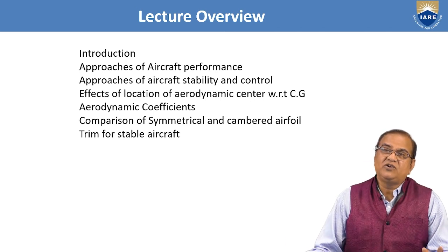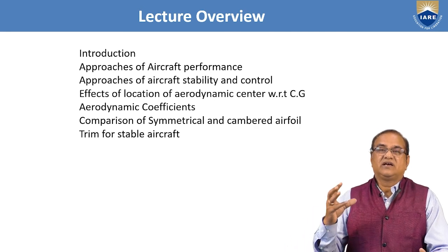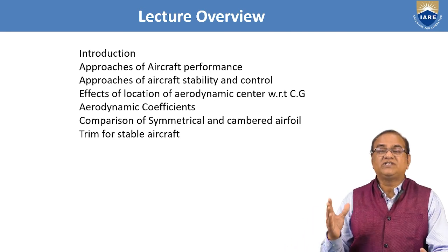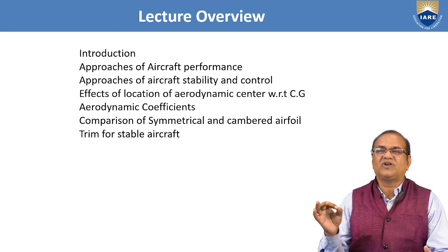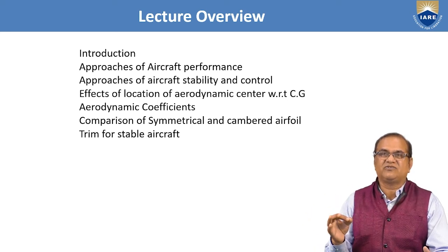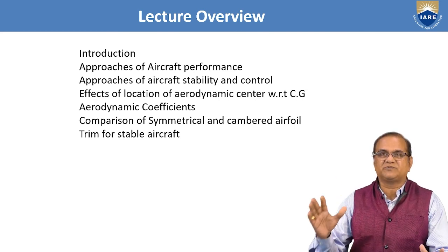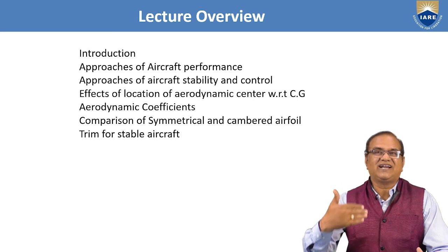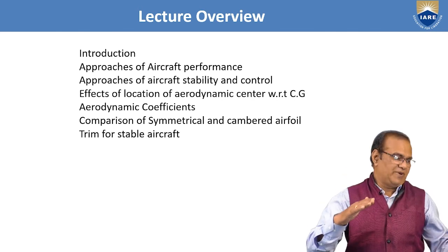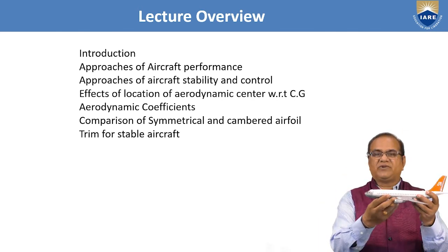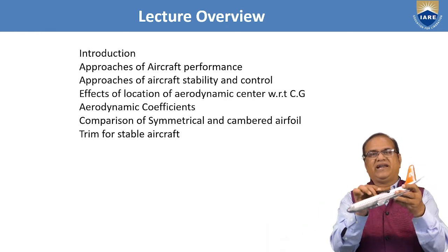So if we want to design the aircraft, we must make sure that the aircraft is statically stable. In this unit I am talking only about longitudinal static stability. If I miss saying longitudinal somewhere, you understand that I am talking only about longitudinal, meaning pitching. The longitudinal motion happens with respect to the y-axis or the lateral axis of the aircraft. In pitching motion, the nose goes up and down. This axis will remain constant and it will pitch up and down like this.